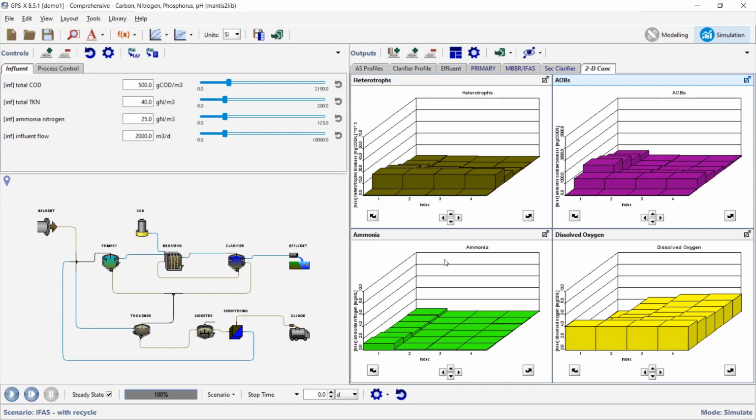So just like an SBR and many other things, calculating what the SRT is becomes a little bit of a question of philosophical interpretation. What does it mean when you're including the biofilm, those units that are the biomass that grows and then dies inside the biofilm and produces inerts, and then that goes out in the sludge? It doesn't have quite the same meaning as it does in a conventional activated sludge system. Okay, so anyway, that's something that you can use, just a very simple analysis, and you can dig through and look at a lot of interesting details.